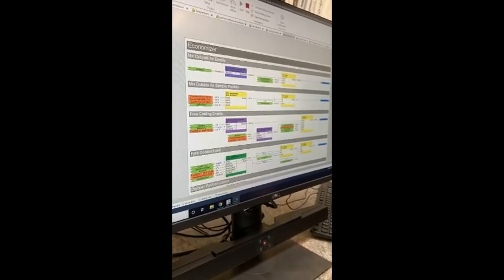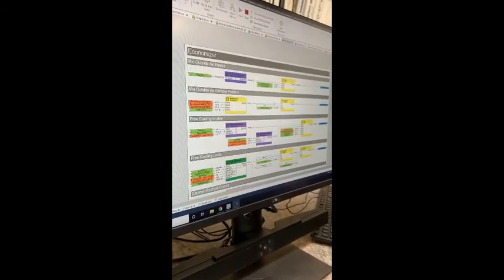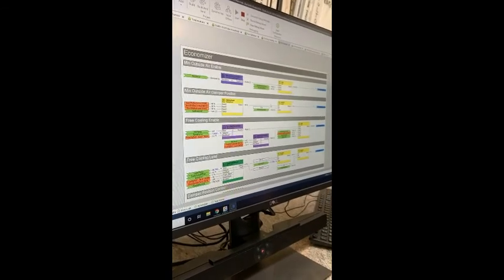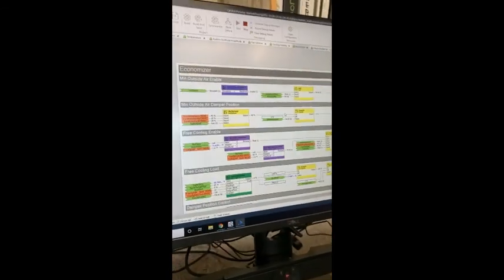I have it turned down. If someone does do this, it can be a useful troubleshooting tool. If something's not working, you can't understand why from the graphic, you can go in and look at the code and see exactly why a hot water valve isn't being commanded to open, even though you think it should. There could be some sort of safety condition that's stopping it.